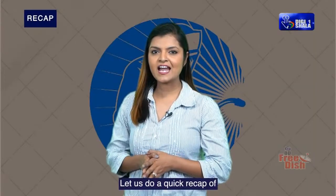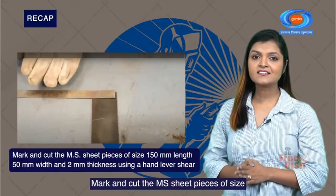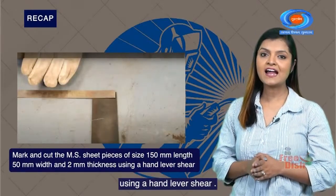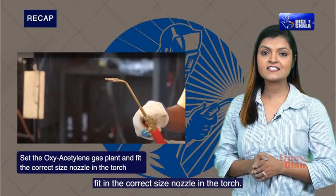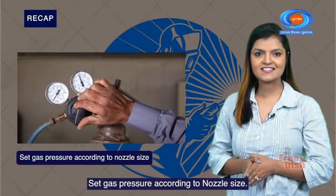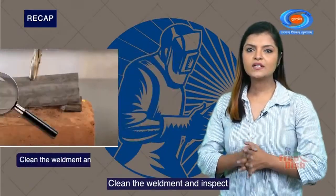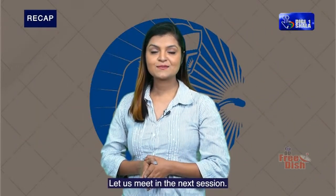Let us do a quick recap of what you have learned from this topic. Mark and cut the MS sheet pieces of size 150 mm length, 50 mm width and 2 mm thickness using a hand lever shear. Set the oxyacetylene gas plant and fit in the correct size nozzle in the torch. Set gas pressure according to nozzle size. Perform the fusion run without the filler rod in flat position using leftward technique. Clean the weldment and inspect visually for weld defects. Thank you, students. Let us meet in the next session.